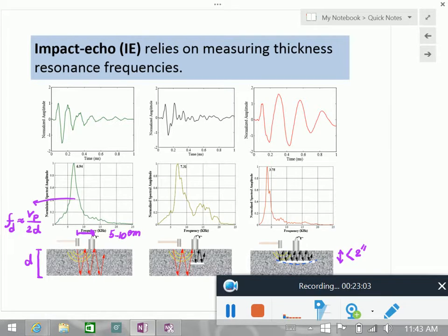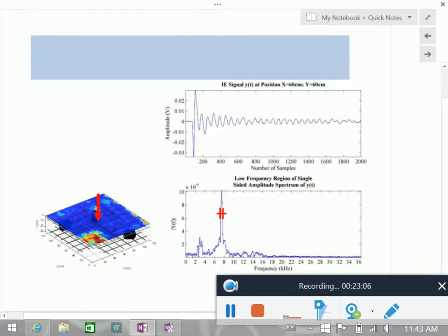So what we did for honeycombing is we just focused on whatever you would get at the location of the thickness of the slab. We had nothing else anyway, but you just look at the thickness resonance and you look at how wide it has become. So basically you just look at attenuation, because the change of frequency didn't give us much information. Is it clear?